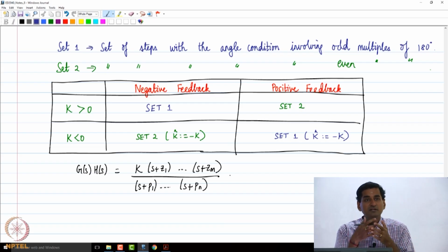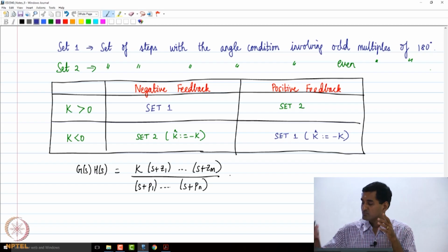Depending on your design choice, we will do a case study tomorrow that will run through the entire process. Now that we have done with root locus design, I will take a physical problem. We will start from the beginning, derive a mathematical model, get the plant transfer function, then design controllers, then find out what ranges of controller gains will stabilize the closed loop system, then how to construct the root locus to satisfy certain performance requirements, right?